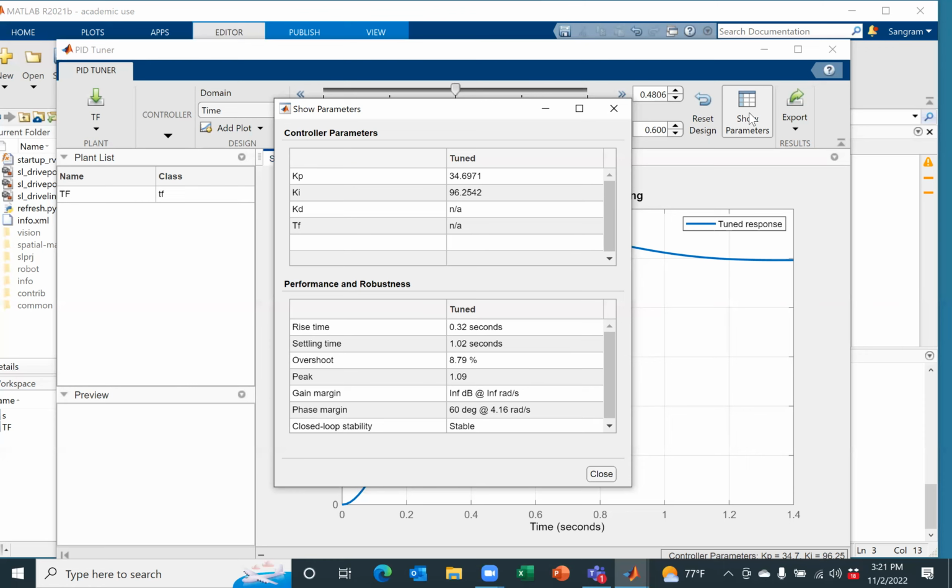It means the transfer function when the nonlinear system is operating within one particular operating range is different from when it is operating in some other operating range. So you have a different transfer function, and a different transfer function, but all these transfer functions together give you a fairly decent, not exact, approximation of that nonlinear robot.